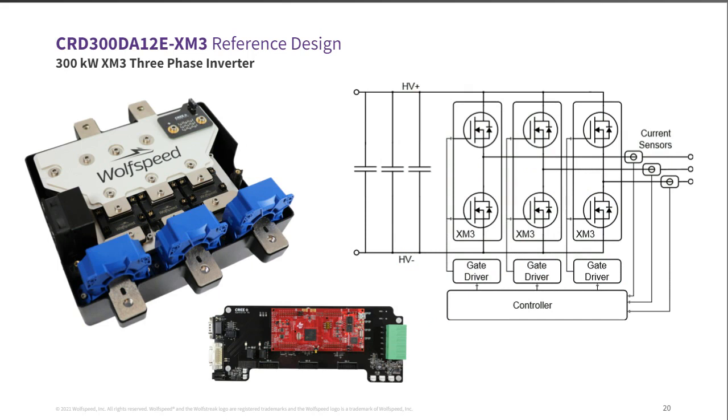And this is simply a three-phase inverter. But what we have here is some DC bus capacitors. It's not really targeted for any particular application, but assuming something like traction, we do have some DC bus capacitors, and those are sized appropriately for the ripple current rating and energy storage for the 300 or 360 amp output current that this kit is capable of.